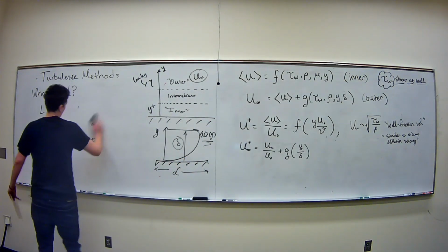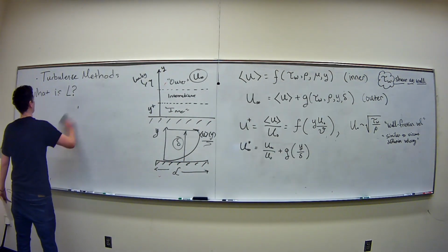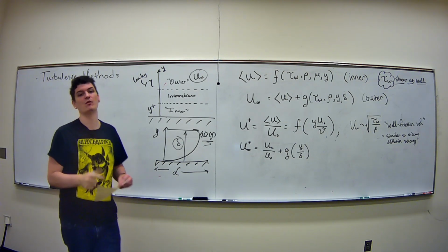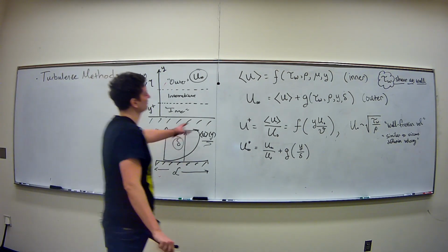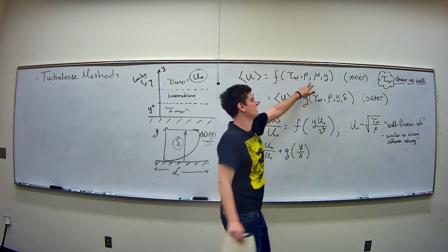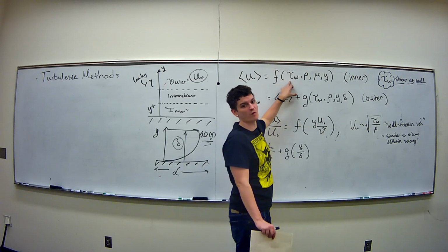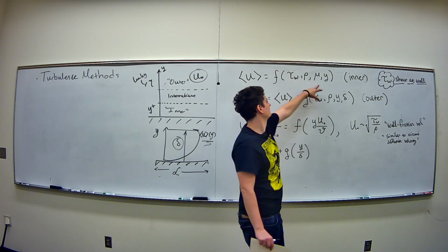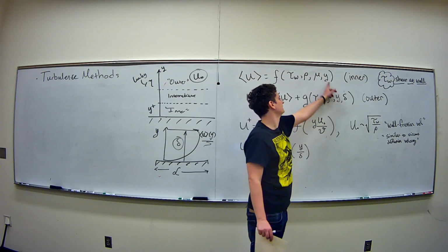So all that's happened so far is I've posed two functions about turbulent flow next to a wall. I've said, what on earth does flow behave like close to the wall? Well, viscosity is going to matter quite a bit, and certainly shear at the wall would matter as well, right? And then there's density and the y. Y's got to matter in both of these.